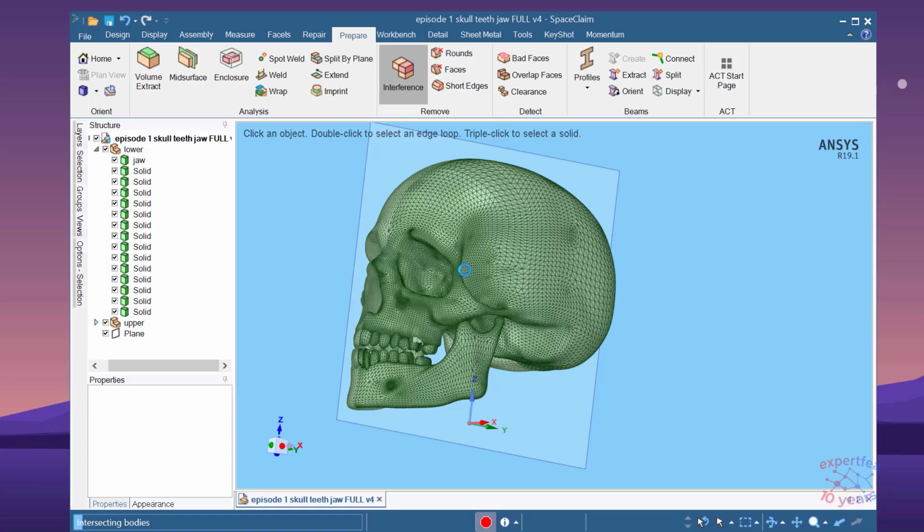What you need to keep in mind is that when we're taking this geometry to the FEA for meshing, we are obligated to do a tetrahedral meshing because of the triangles that exist on all the faces, and the triangles will impose only tetrahedrons on the mesh, or mostly tetrahedrons. Maybe some pyramids can appear too.